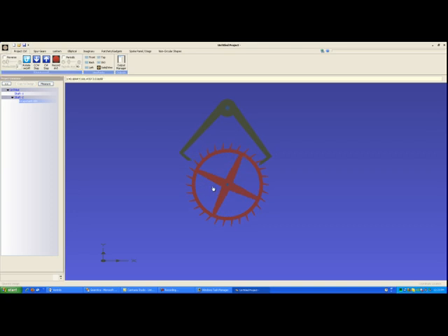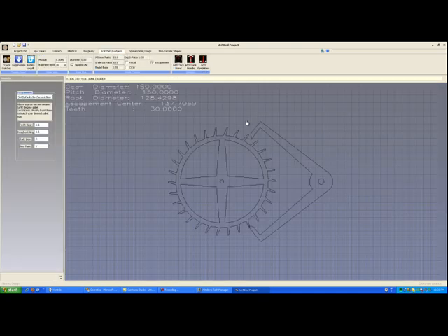So now we need to look at what you can tell on the screen from this. If I click on Escapement and highlight it on the project tree, you can see that it's telling me the time of rotation here at the bottom is 1 minute per rotation. This is actually a lie because we don't know what the time of rotation of this is. Although we have 30 teeth on it, there's no way of telling how fast that's going to spin until we add a pendulum. So let's add a pendulum and figure that out.